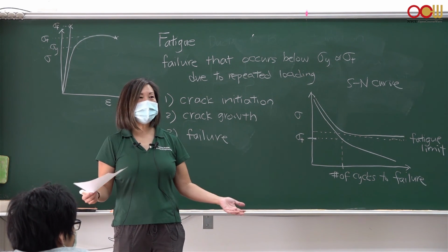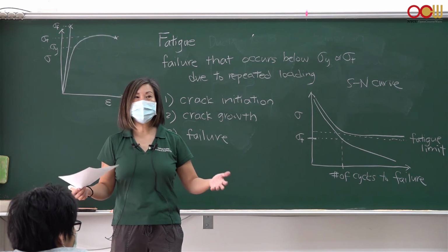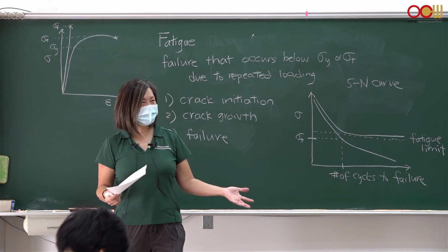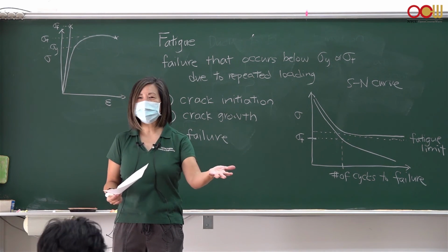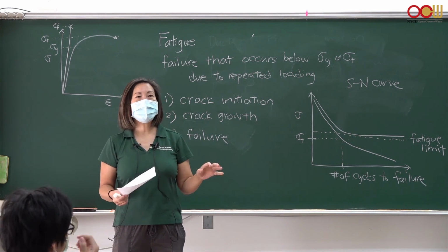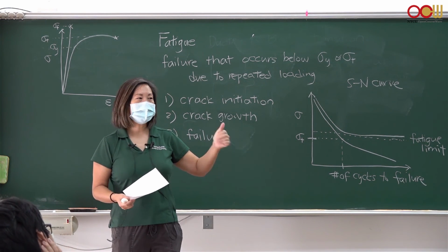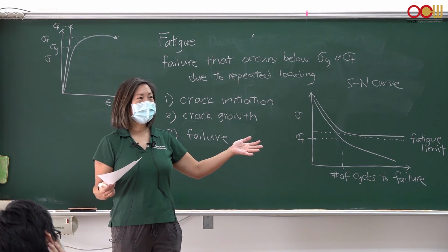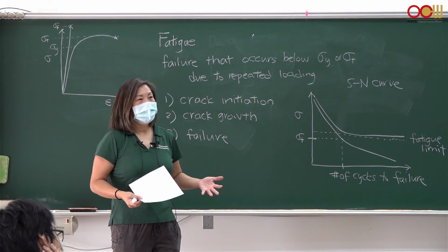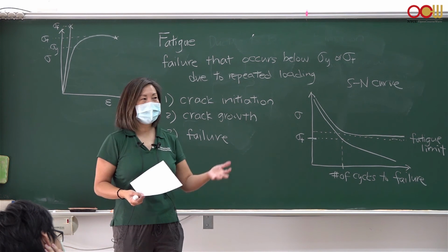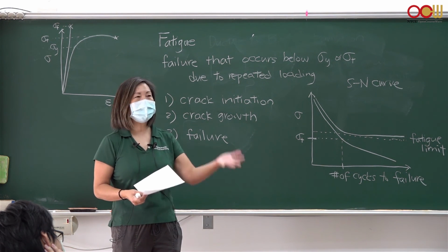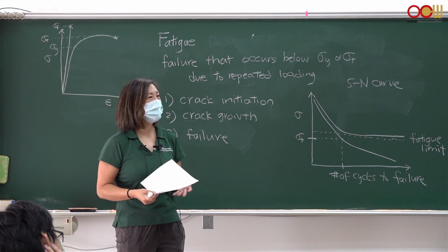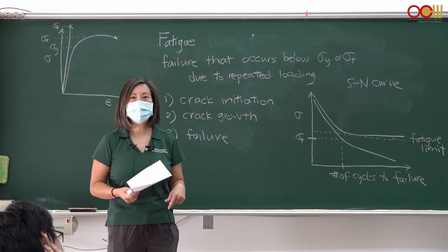Like let's say you're going to use this material at an elevated temperature for 10 years. You're not going to test your strain for 10 years before you say whether this material can be used, right? So in those cases, they would increase the temperature. They would say, let's try to heat it at 10 times the temperature and then guess backwards at what point the material will fail at a lower temperature. So they try to speed up the experimental process. It's not perfect, but it's sort of what the engineers have to do.